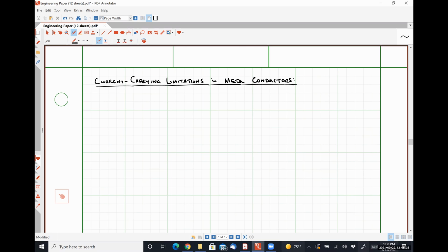And so that tells us that we need to run, say, 12 gauge wire for this application and 4-naught wire, which is that big around, for very high voltage, high current applications. Well, in an integrated circuit, we're talking about very, very small sections of wire, right?